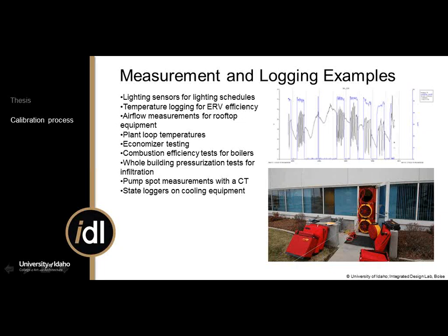And then we've also done whole building pressurization tests now for 2 buildings where we've come up with a scientifically backed number for the infiltration. Anyone who's done energy simulation knows that infiltration is a pretty big lever for calibration, and it's a huge question mark too. It can vary widely what the actual baseline infiltration is. So these tests are pretty critical in trying to quantify some of the specific characteristics of those buildings. We did one on an office building. We just recently did one on the hotel that we've been working on, and we used that number in our energy model.